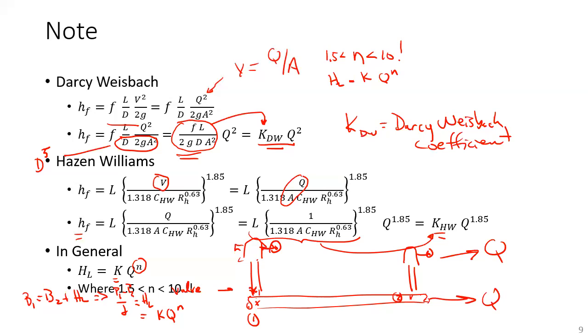And that's why the Torricelli equation, if you remember it, the orifice equation, what's happened is you've dramatically increased C. And so that C is representing all the energy losses in the system. So that's how we practically fold either Darcy-Weisbach or Hazen-Williams when we're looking at systems and you actually don't know what's underground. All you're trying to do is develop a model that reflects what's happening underground.